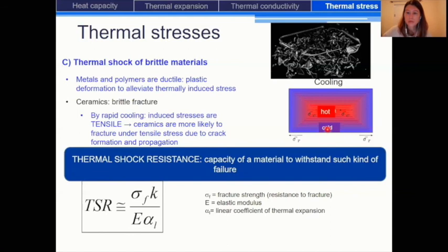And so even in these borosilicate cooking plates that are said to resist thermal shock, you may have already experienced this very bad experience that you took the plate from the oven and then you poured cold water on it and it totally fractured and was destroyed. And so this is due to the fact that ceramic is brittle and does not resist tensile stress.